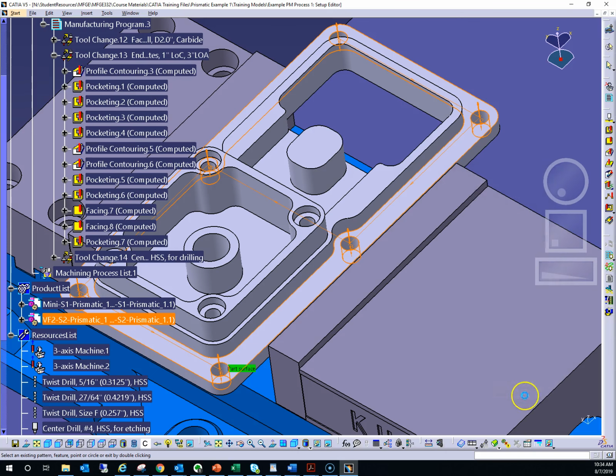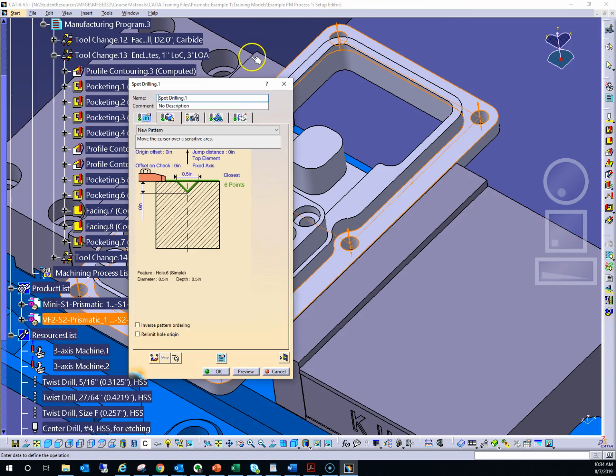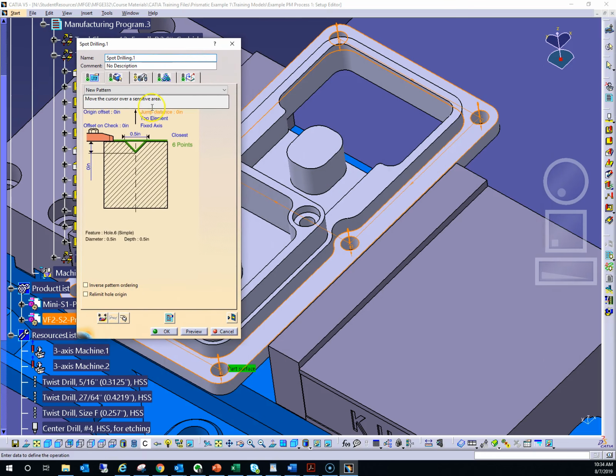Okay, so let's hit close and then double click in the background. And our dialog window reappears, and we now have green for both the entry surface and the hole. We also have to set the depth of the hole, because for a center drilling operation there's no final surface on the part, of course, as there is for either a through or a blind hole. So we have to specify the depth that we want to go with the center drilling operation with this value here. So double click on this, and we're going to go down into the surface 100 thou.